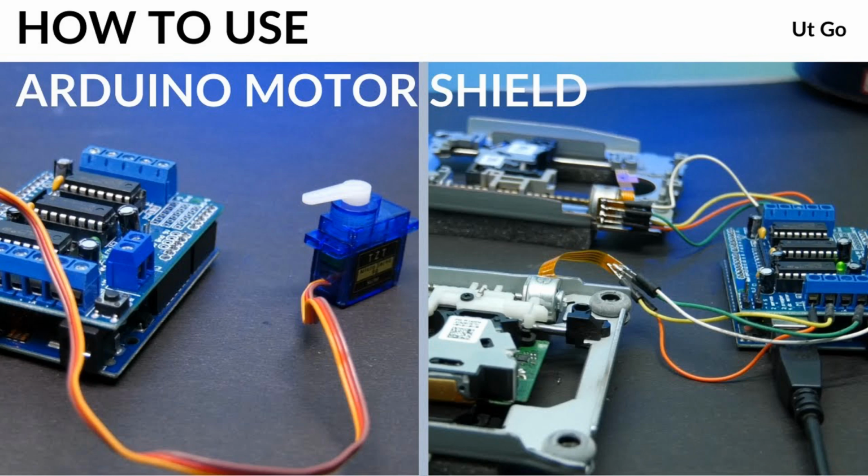Servo motor drivers are essential for any application requiring precise, reliable, and efficient motion control. The type of servo motor driver chosen depends on the motor type, application requirements, and the desired level of precision. Brushless DC, BLDC, motor drivers are used to control BLDC motors, which are commonly found in applications requiring high efficiency, durability, and low maintenance. Unlike brushed DC motors, BLDC motors have no brushes, which eliminates the need for mechanical contact between the rotor and stator, providing smoother operation, greater efficiency, and longer lifespan.